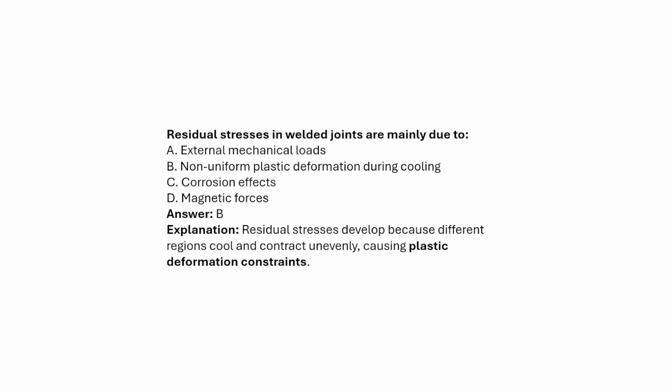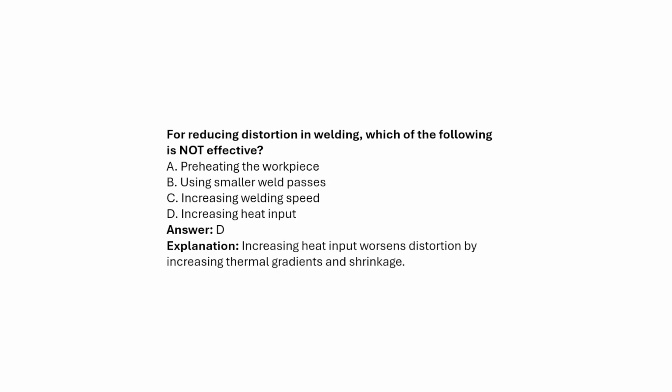Residual stresses develop because different regions cool and contract unevenly, causing plastic deformation constraints. Next, for reducing distortion in welding, which of the following is not effective?